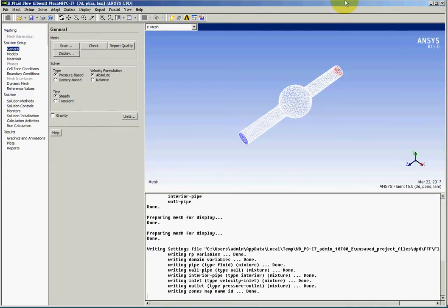And if you have experience in SolidWorks flow simulation or COMSOL flow simulation, there are 6 steps which you can follow for the solution of a flow problem. The first step will be drawing of a geometry and opening a problem, and also defining the inlet and outlet.